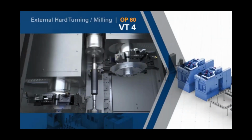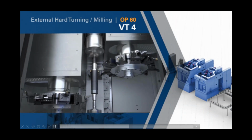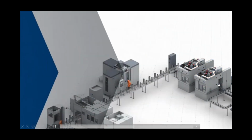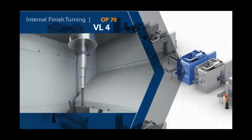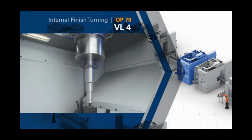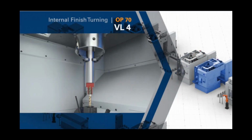So what I haven't demonstrated so well in any of my videos so far is our track motion. And this track motion is a really nice tool to bring parts from one Emag machine to the other. It kind of runs through a tunnel on the back side of the machine and transfers the parts from machine to machine. The big benefit, as it compares to a lot of robot load, and do not misunderstand me, robots have their place, is that you can free up the operator on the front side to be accessible to the controller, to be accessible for tool change, and let the automation run in the background, serving other machines at the same time.